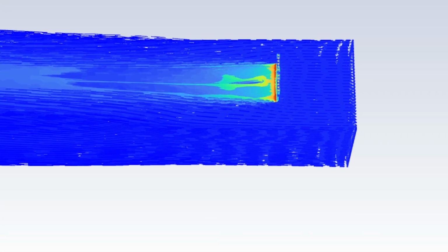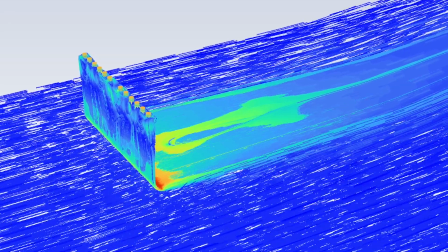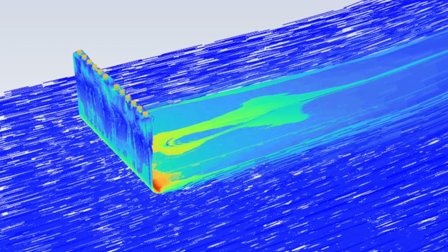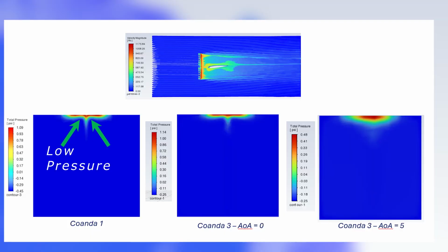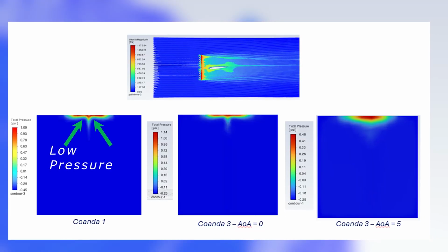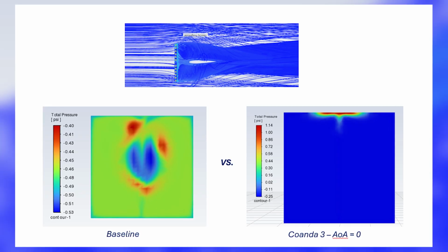Using the ANSYS Fluent software, we successfully modeled the CFD simulation of our wind tunnel and SFS injection. The results showed the Coanda injection geometry creating high-pressure flow regimes at the ceiling. We also saw low-pressure dips around this region at the trailing edge of the airfoil, which would later match what we saw in testing. But compared to a radial injector case, a large low-pressure region was formed around the center of the test section with turbulent flow around the stator.